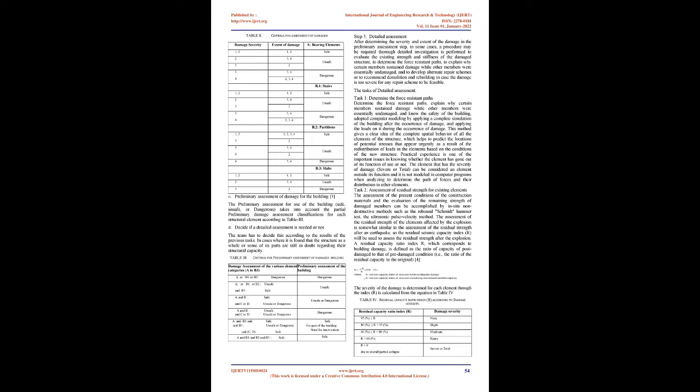Objective: A. Thorough visual examination, use of photographs, notes, and sketches to document this examination. Abnormalities should be recorded as to type, magnitude, location, and severity. B. Measure and record crack width, depth, length, location, and type. C. Surface defects such as spalling or scaling, shape, area, and depth. D. Corrosion of reinforcement, including the extent and amount of reduced cross-section. E. Visible deviations and deformations.